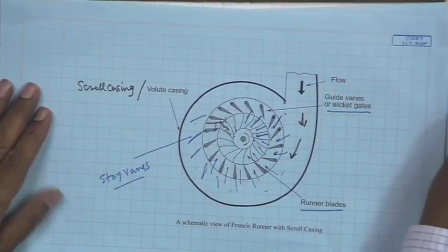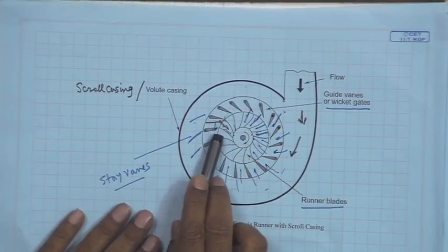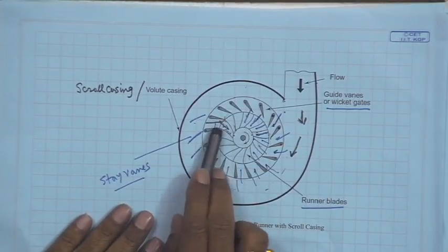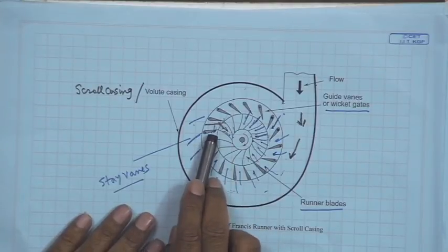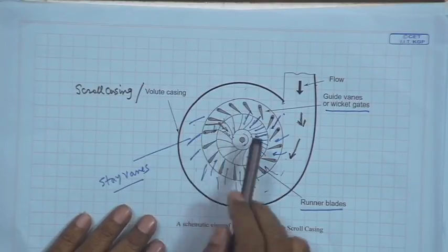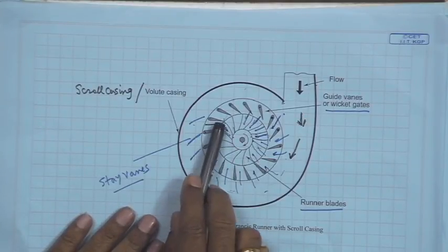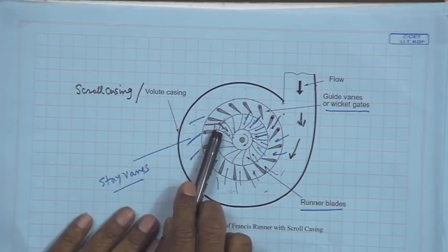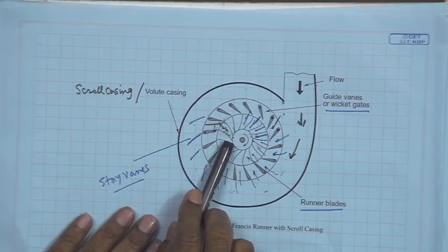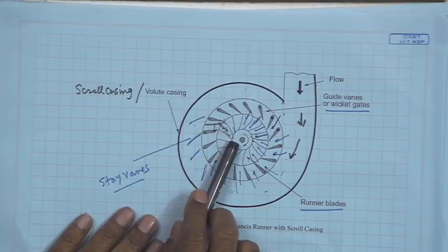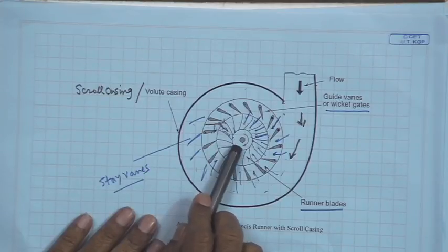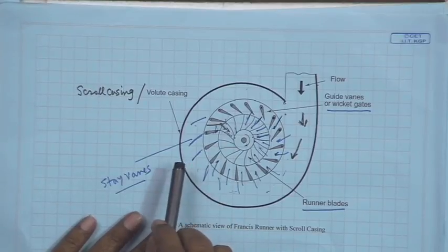Now, one thing has to be remembered, please have a look at this turbine. This is the typical runner blade or runner of the turbine, and you see when it flows through, it has a radial and tangential component of velocity at inlet. When it comes outward, it has purely radial velocity, which is turned 90 degrees in the axial direction while it enters into the draft tube.